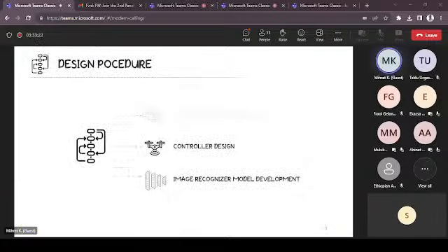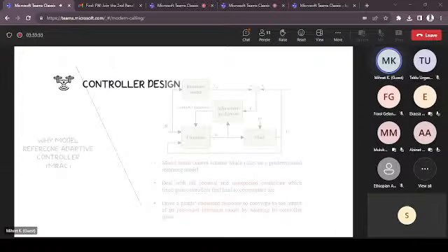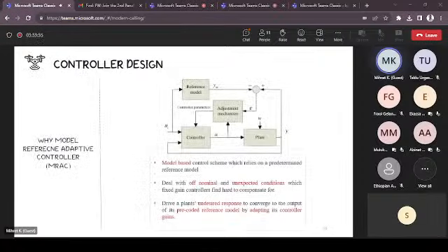So having the dynamic system modeled, the problem of stabilization arises, and it's basically dealt with by controller design. So for the chosen application, we know that it requires an outdoor flight, which is characterized by diverse weather conditions. So the controller chosen for this specific type of application is the model reference adaptive controller, which is able to put up with unexpected disturbances and uncertain scenarios.